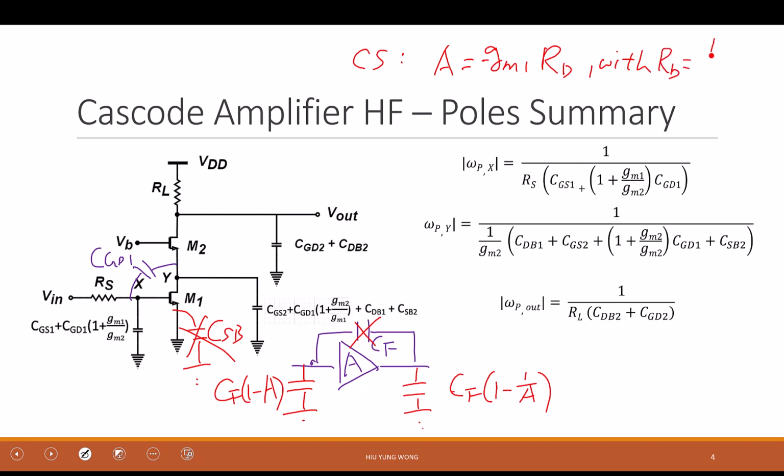Into the source, yes. So that's why I need to slow down, right? Very good, because you look into the source. This part, you look up, and you already solved this or saw this in the assignment many times. It's the input impedance to the source of the common gate amplifier, so it's 1 over GM2, right? So that's why the gain A is negative GM1 divided by GM2.